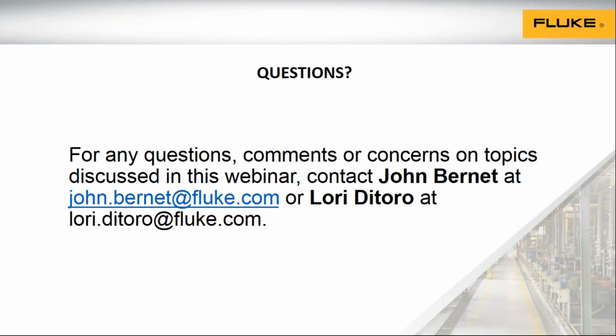So, the next question is, as opposed to strictly calendar-based maintenance, do you have any experience with runtime-based preventive maintenance? This person uses runtime meters to generate a good percent of their preventive maintenance work orders. Oh, yes, that's a good idea, because you're right, basing this totally on calendar isn't the whole answer. You can add several different components, where you can add in the calendar, which is based on manufacturer recommendations. You can put in runtime. You can put in history.